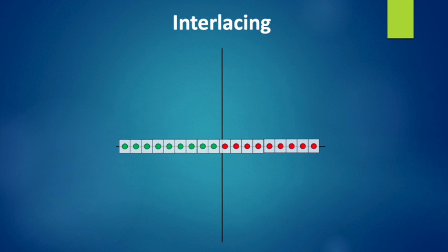The color LEDs used have a width of 1.6 millimeters and are positioned 2 millimeters apart on the display. The principle of interlacing, which is also known from cathode ray tubes, is used to increase the resolution of the display. The principle, at the same time, increases the perceived frame rate and thus reduces flickering. The following animation illustrates the principle. Please note that the color of the LEDs in the illustration is just for clarity and has nothing to do with the color function. The display of color is explained in the next section of the video.